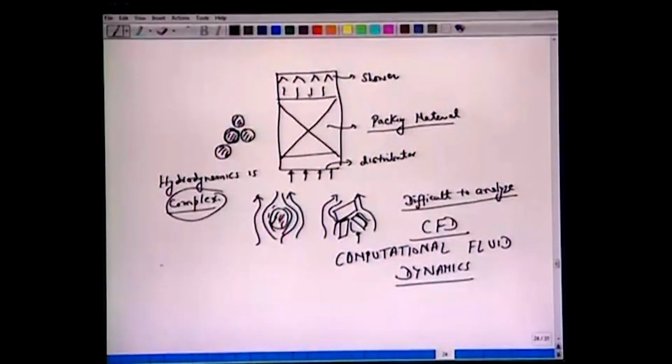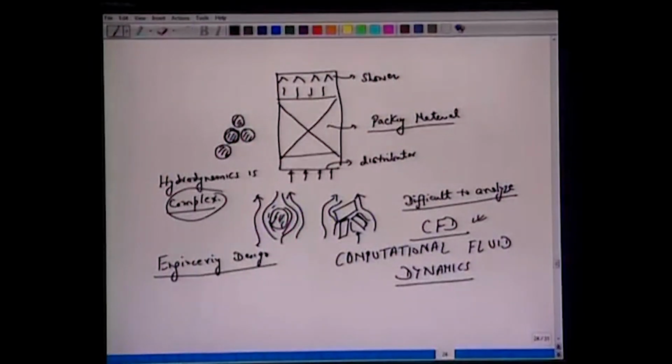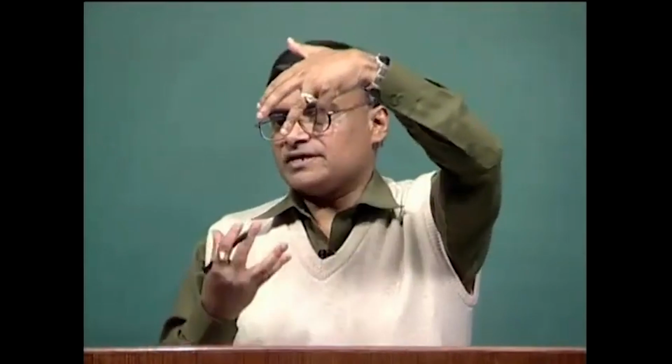So generally what happens when it comes to engineering design, then hydrodynamics is not solved to the extent the way we do it in the case of CFD. Now what we do here in the case of packed column design or similar unit operations is a macroscopic analysis. All it means, water flows from the top and gas flows from the bottom. So if you have two countercurrent flows, from the engineering point of view or from the operation point of view, loading and flooding should be the main concern.